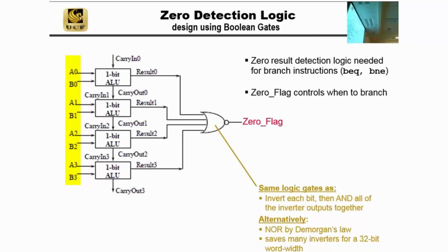Let me say it one more time. I've already built an adder, and I made it into a subtractor, so now I have a subtractor. So if I take A minus B, if that result is a 0, what does it tell me about A versus B? Is A equal to B? Double equals, actually. Thank you for reminding me. Double equals. Pretty cool. Suppose this number is greater than 0. How does A relate to B? A is not greater than B. A is greater than B. How about we get a number that's negative? A is less than B, or B is greater than A.